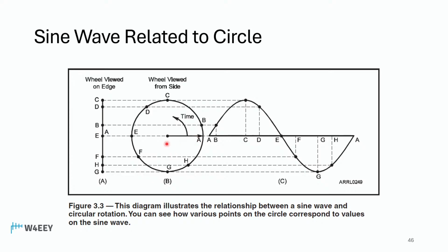We've got, I guess we could call this a phasor. We're going to be rotating it around. And as we do so, we're going to reach 10 volts here, I'll say. 0, 10 volts, back to 0. So at the point A on the sine wave, we're going to be here. Now this vector is rotating, so at some certain point it's going to get to point B, and that'll trace this dot on the wave.